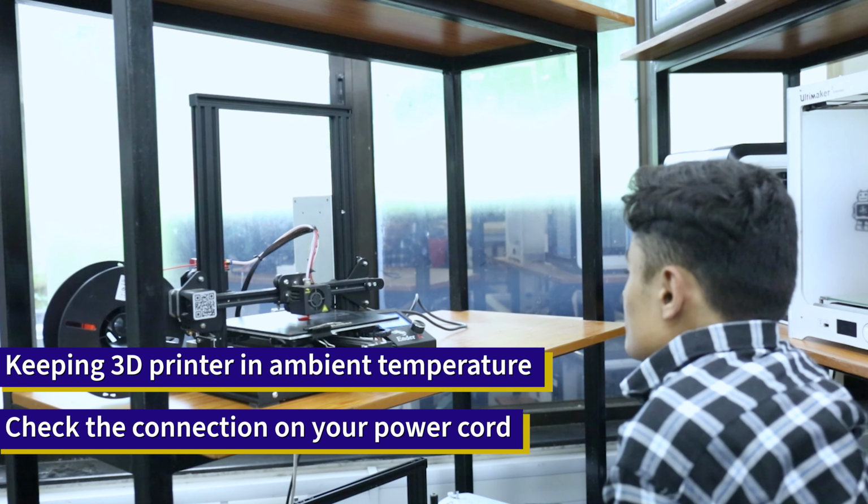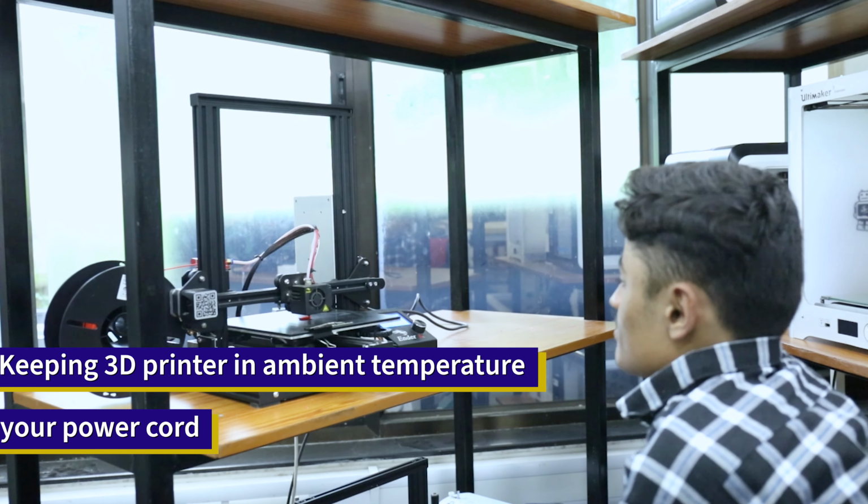Also, check the connection to your power cord as well as the thermistor. If that's all connected, take a look at the fan to make sure it's not damaged and review all other components as well. If you face any problems other than what I mentioned, it is important that you contact a senior lab staff to solve the issues.